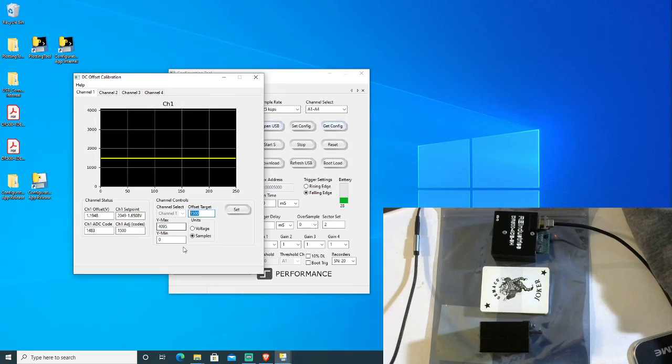And if you're stuck at half of your bias voltage and your overshoot's larger than your undershoot, you're limited by half of VCC until you have a clipping problem. So being able to walk this down means customers can now get much more out of each data channel.